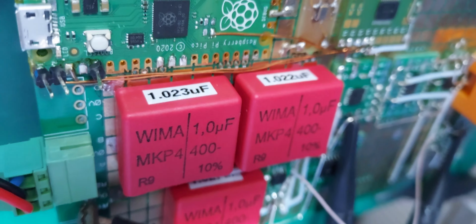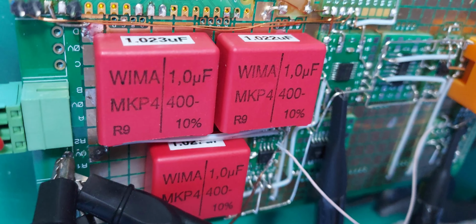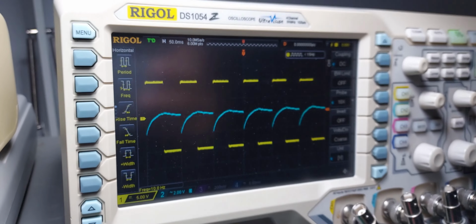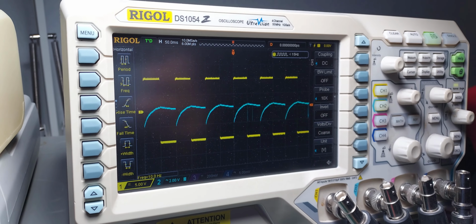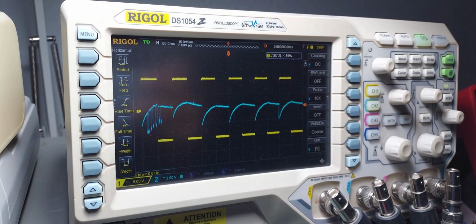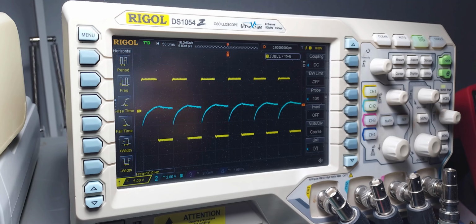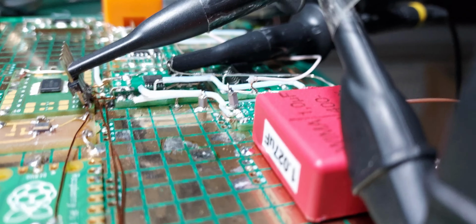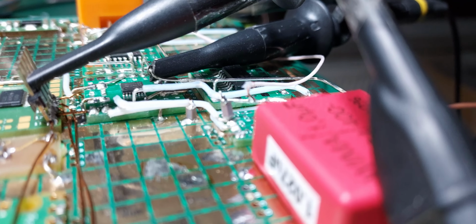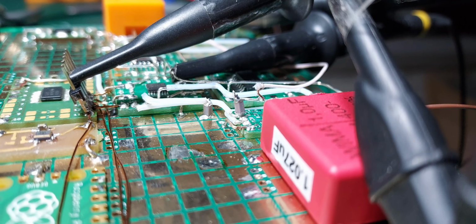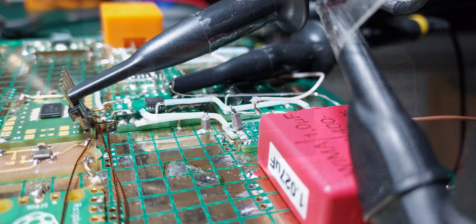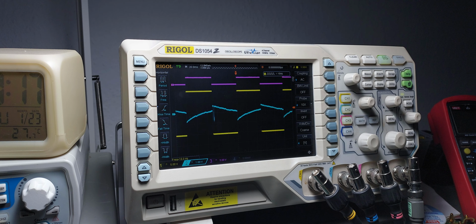Each capacitor was measured using a DMM to find the most closely matched pair to use in the sample and hold circuit, but I obviously messed up and soldered the capacitors in the wrong positions. Fixing that mistake didn't help the noise as I had expected. To test the theory of larger capacitors loading the op amps, I botched in smaller 100 nanofarad C0G capacitors to see the effect on the output ripple, and it was predictably worse.